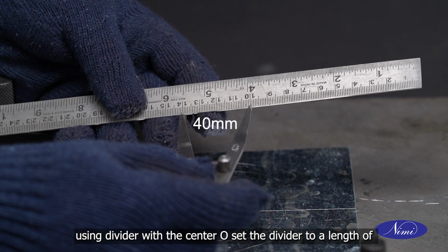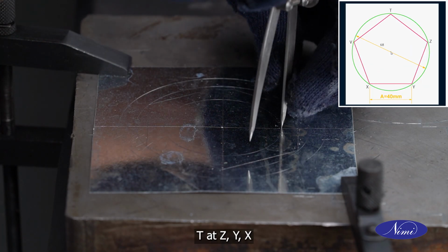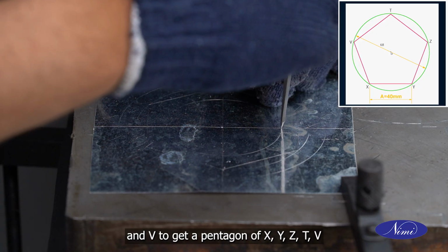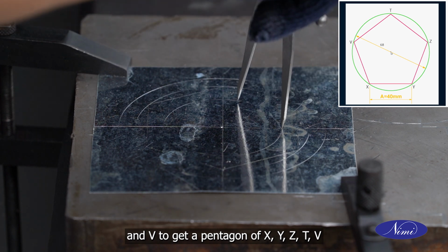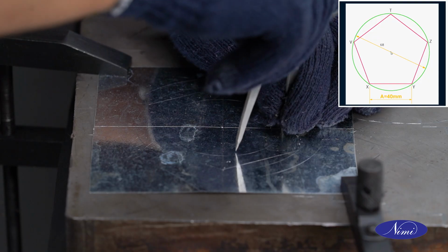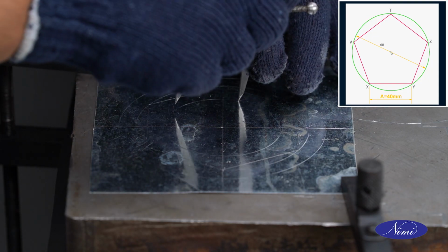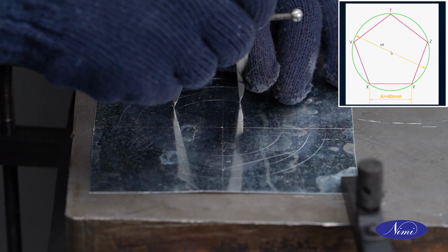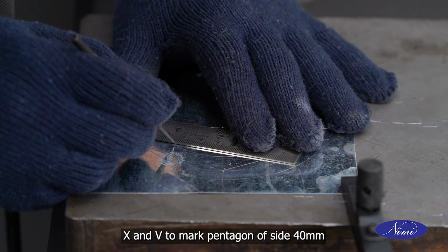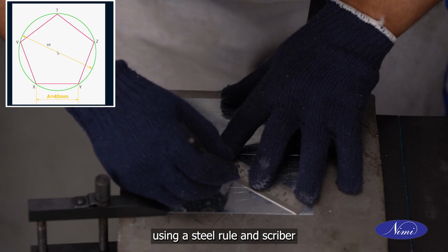Set the divider to a length of 40 mm using a steel rule. Cut the circle from point T at Z, Y, X and V to get a pentagon of X, Y, Z, T, V. Join the points T, Z, Y, X and V to mark a pentagon of side 40 mm using a steel rule and scriber.